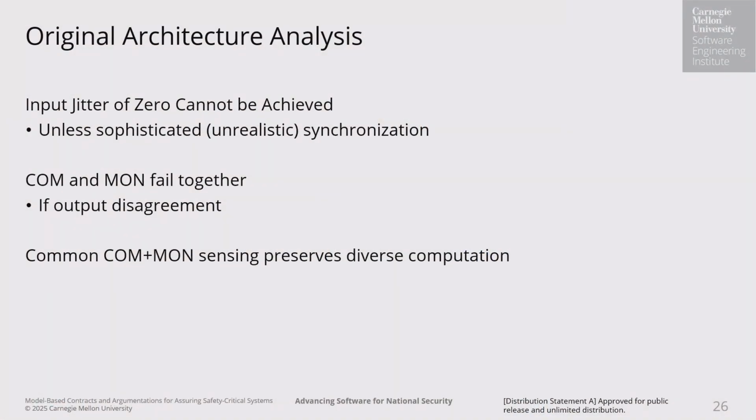So what we decided is to modify the architecture so each pair has a single sensor. In the end, if the sensor fails, the whole pair fails. But if one of the two elements fails, also the whole pair fails. So it was a fake failure independence. So we decided to go after that, after exploring a few other options. It's a simple check. We were able to check that the assumption was satisfied and that we were able to avoid that problem. The new architecture, just same sensor, done, right?